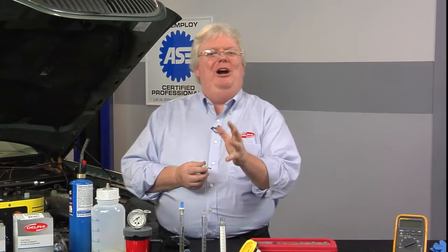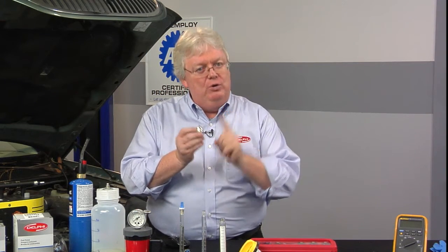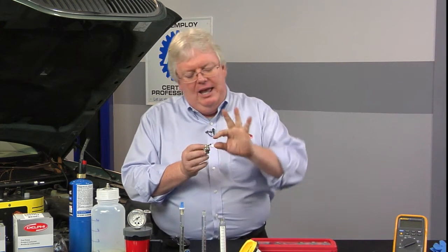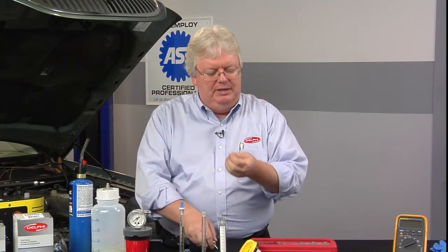Anybody who's worked on cars for more than a week has seen this, where you have the good old-fashioned fuel rail with the return line and the vacuum operated pressure regulator and the little vacuum hose. You pull it off, tap the hose in your palm, some fuel falls out, bing, that is a rich mixture, and that's a code 172, 175 waiting to happen. Those are just as common as can be.